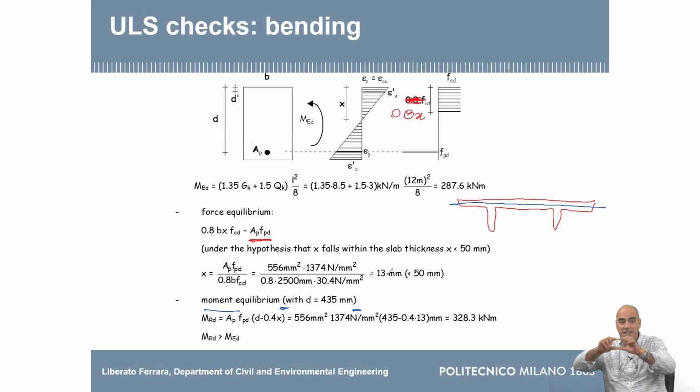So you see, the fact that you have this very wide area, you really need a very thin area of concrete. In some codes you find that, for example, if this neutral axis is lower than the maximum aggregate size, just use the maximum aggregate size, or instead of using 0.85 as a long-term factor, use 0.8. You know, you have some adjustment just to take into account that this is a very thin element.